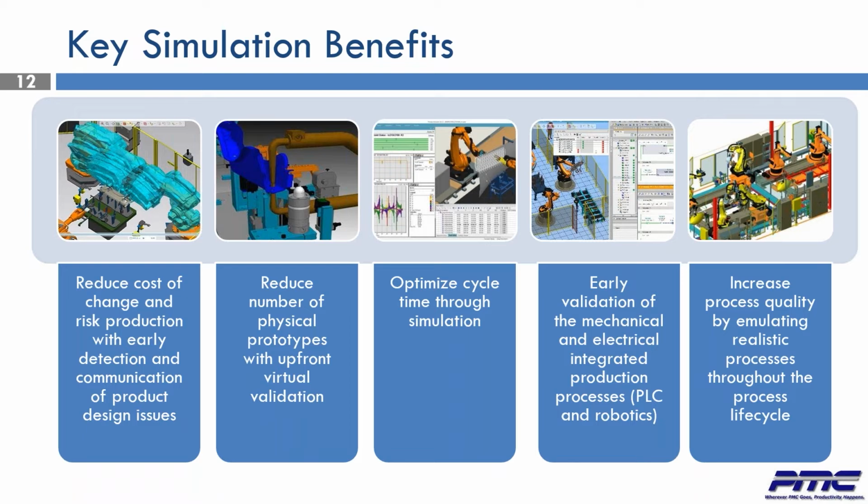Here we have two situations. We can create a new trajectory already inside the simulation environment, or in some cases we can download the real robot program, upload it to the virtual environment, and rework its trajectory there. In this case, this brings us more speed in the changes and avoids possible problems in the real environment.